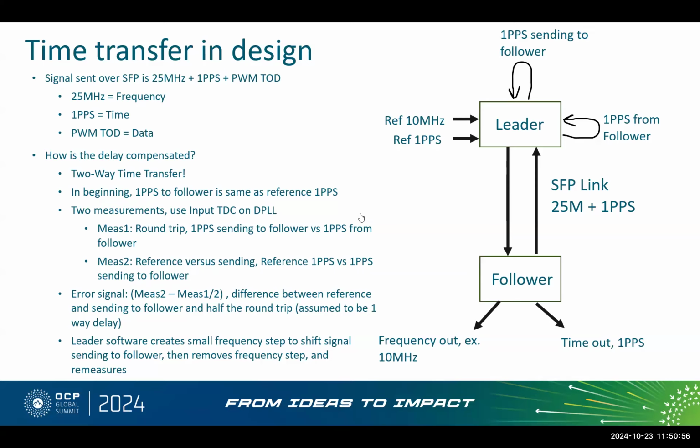But I was saying, if you wanted to send clock quality information, let's say you have 2 machines with this card in them, both connected to each other over this DPLL over fiber network, and you wanted one card to know that the other card is now in holdover, you could do that using this in-band data communication, but it's very slow and takes a lot of management. Or you could just send an Ethernet data message. Essentially, it's out of this clock band.